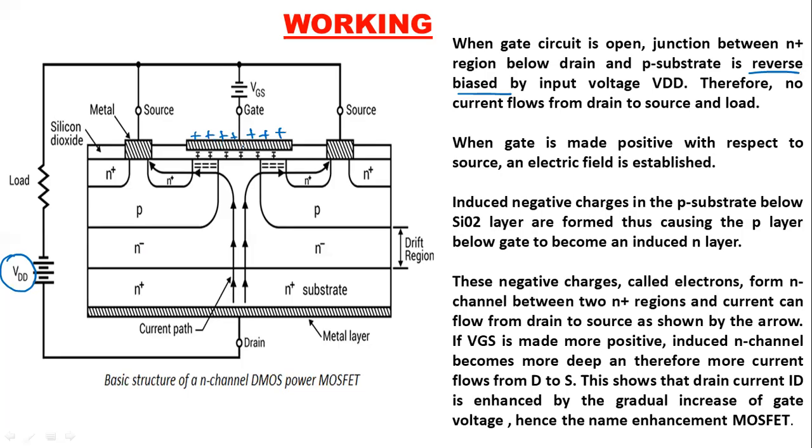So this metallic layer will get polarized, and the other side will become negative. In polarization, this will be negative and this will be positive, right? In the N-channel planar enhancement MOSFET, the N plus region is diffused on the P substrate. So here you can see that whenever the source to drain is positive, always one layer will be reverse biased.